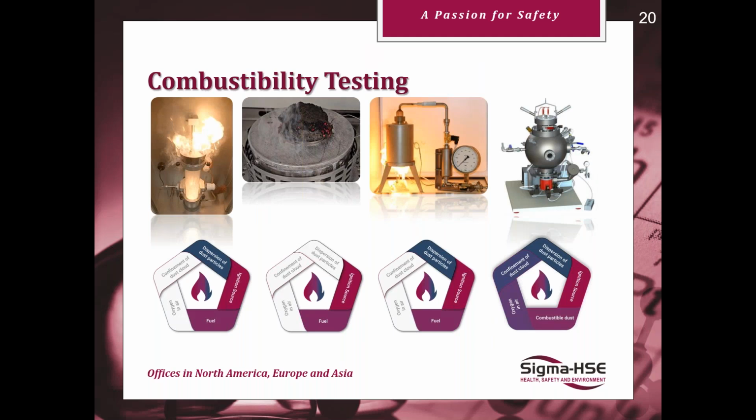Moving next to that, we have the layer ignition temperature, where we have a layer of material on a hot plate. So at that point, we're only studying the presence of the combustible fuel and the ignition source being the elevated temperature, and at what point it stops igniting the material.